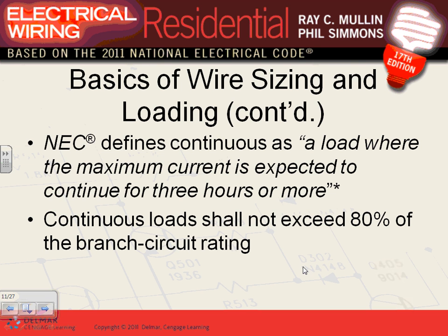You're going to hear continuous load. Let me tell you something about continuous load. Continuous load, guys, in residential, lights and receptacles are assumed non-continuous. The code doesn't tell you that, but it's highly unlikely, and you can argue with me here. But from a design point of view, lights and receptacles used in dwelling units are assumed non-continuous. Highly unlikely they're going to be fully running, with all the lights on the same circuit for 3 hours or more. Again, you can argue with me and say, no, in my house I turn everything on in every room and leave it for 5 hours, that's fine. But for practical design, it's not continuous.